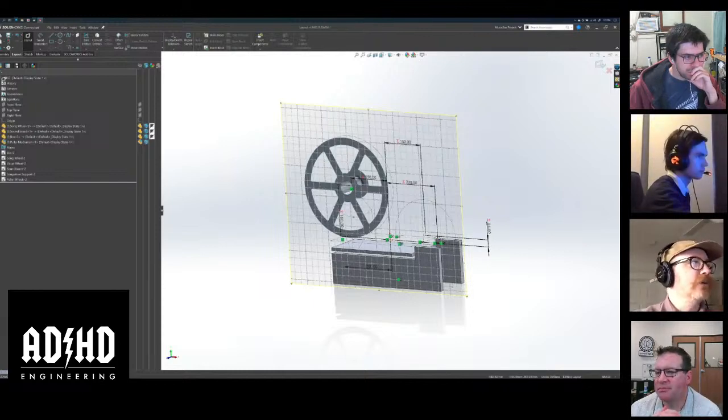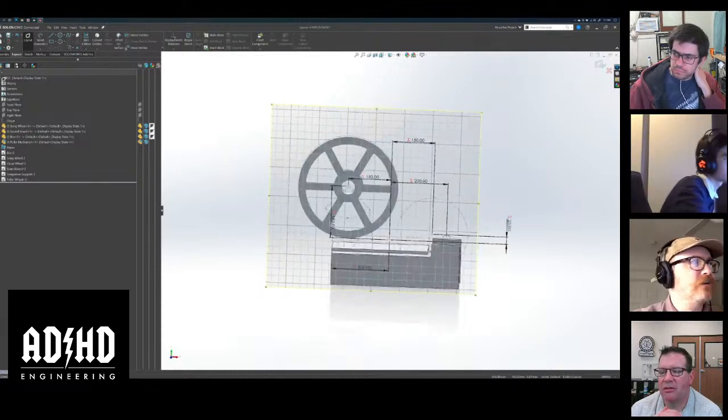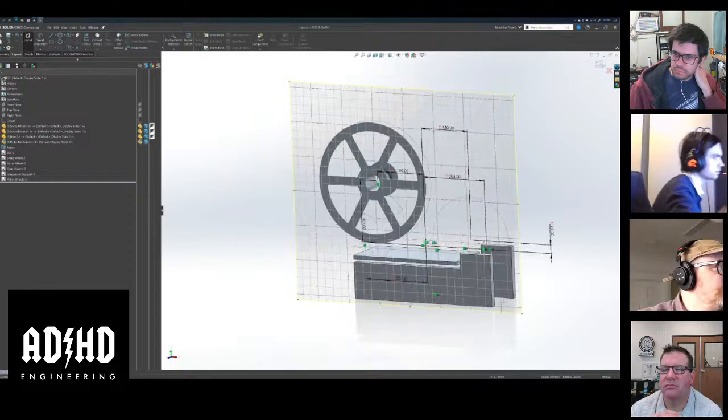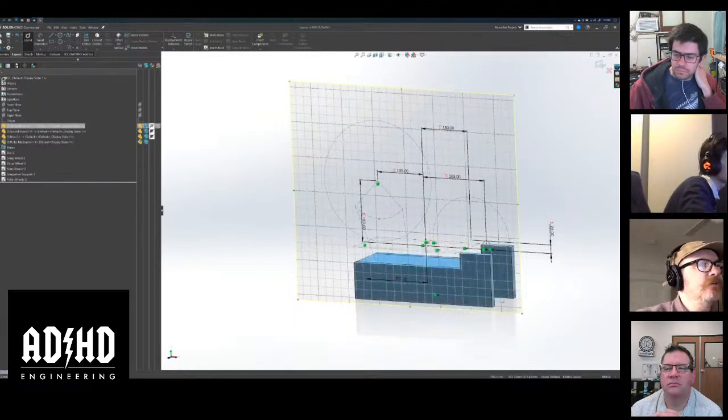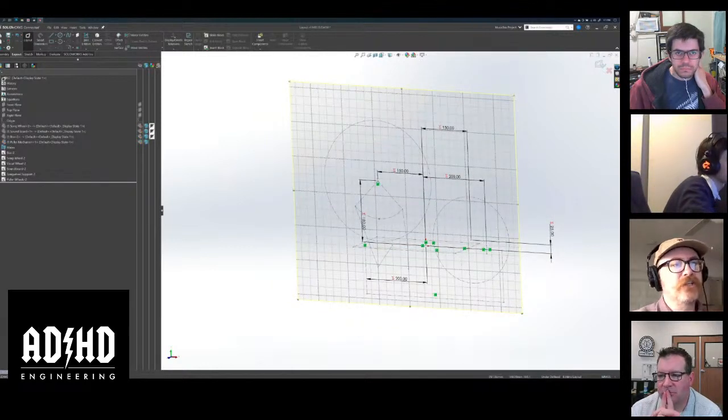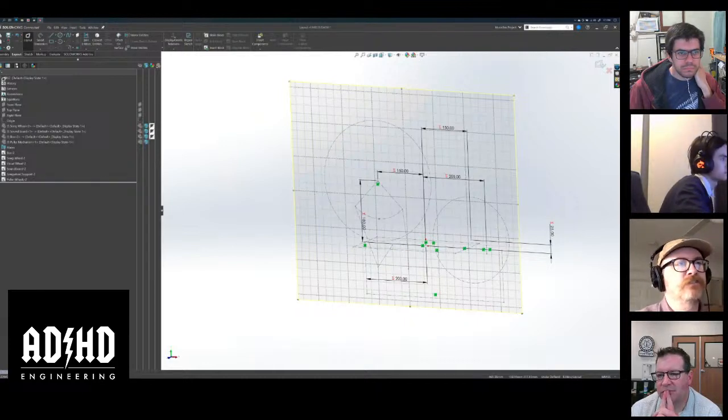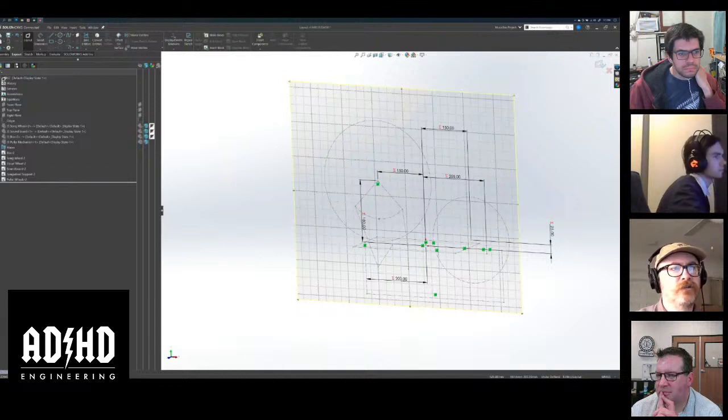Right. Okay. So again, it opens up a 3D sketch, but normal to the front plane. Let me turn off the components so that you can see it better. What you're seeing on the screen is actually not in that sketch. All these things are blocks that I added to the sketch. The only thing on this sketch are dimensions that orient those blocks to the origin. So if you notice, they're all parameterized.